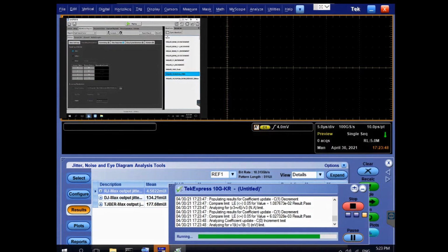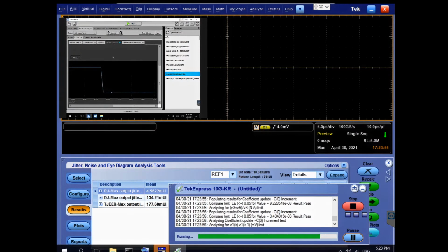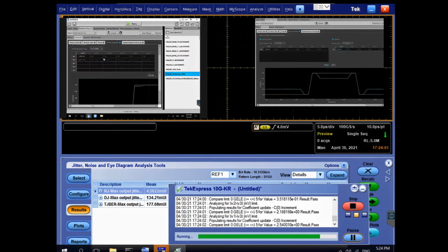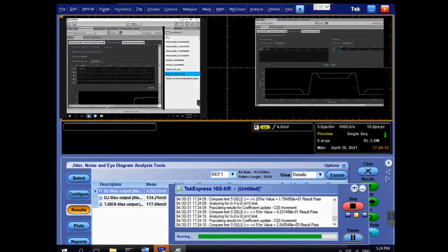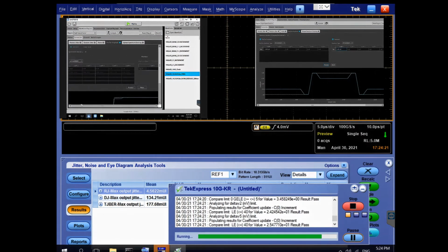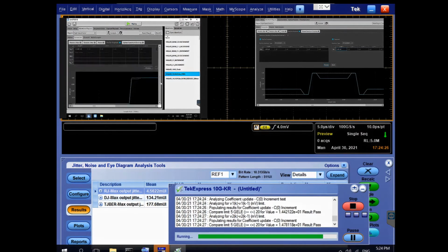And you can also apply scrambling. You can modify the step response or the duty cycle. And I was using the pre-/de-emphasis setup here, where you can adjust the cursors. You have five taps on the pre-emphasis, and also a pre-shoot tab where you can adjust, and I've been using that to generate the waveforms required for the 10 gigabit KR application.